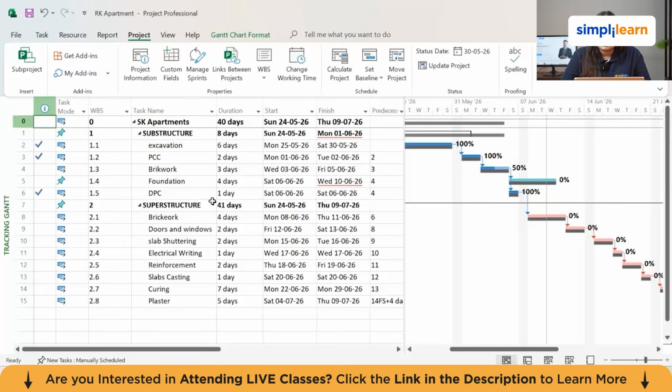With the baseline set correctly before work starts, reflecting the approved contract program, every future update generates meaningful variance data automatically. The one practical rule is to set one baseline at project authorization and protect it. Only set a second baseline when the approved scope changes or a contract variation fundamentally changes the approved program. Everything else is progress tracking, not baseline variation.